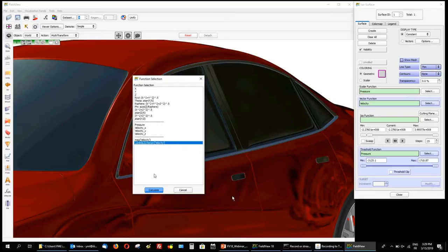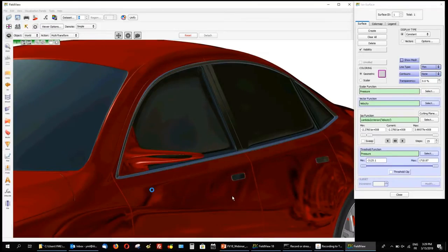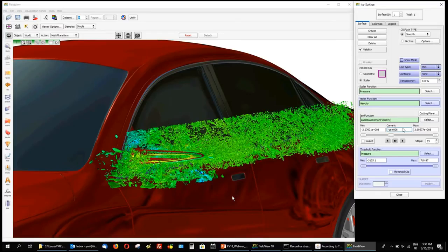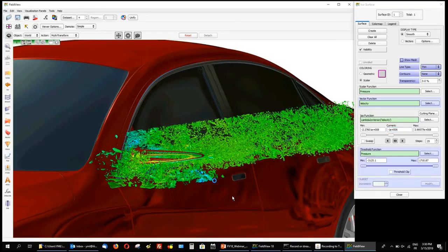It works really great with a user surface. So the computation could be a little bit heavy, but it's a lot faster than a user-defined formula. And then what I would recommend is that you start from large values in absolute value. So here we'll go to a better rendering and do scalar coloring on that surface. And from those high values, you then use different orders of magnitude to find the surface that is going to give a good feeling of the turbulence that you have in your flow.